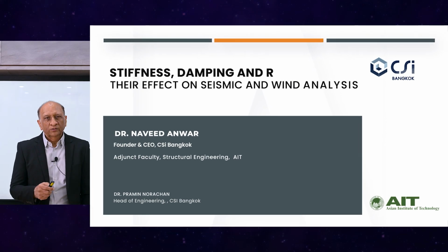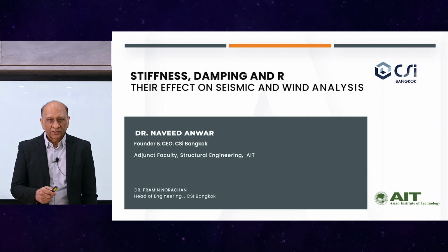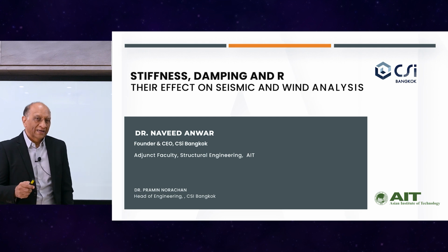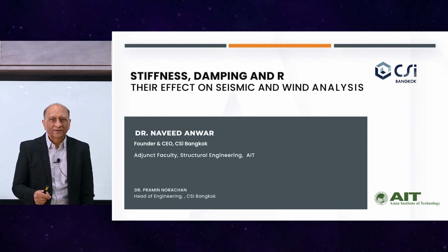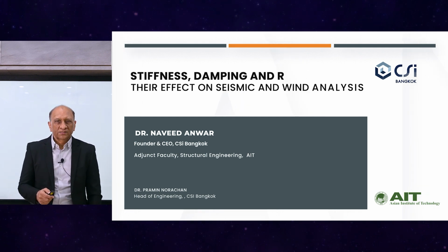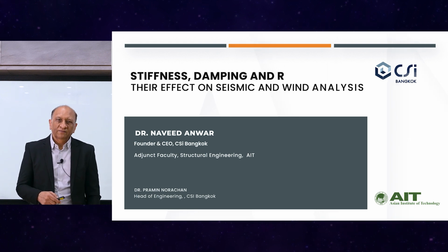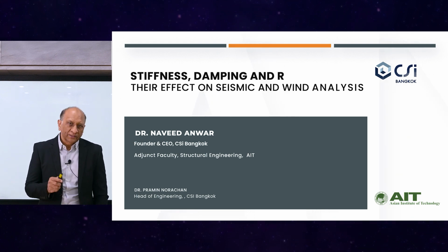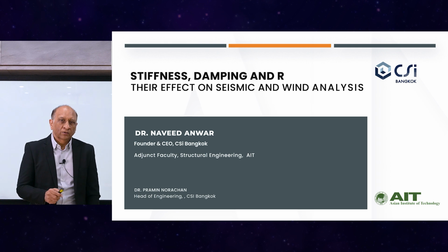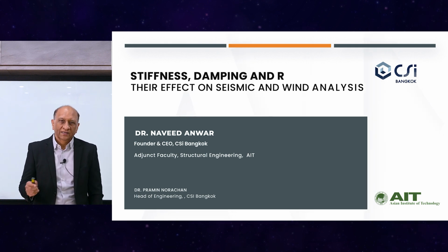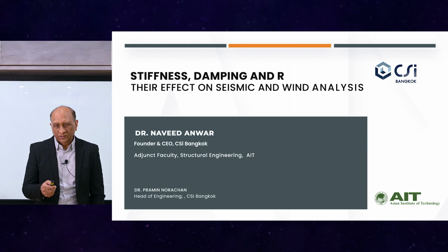Once again, we are going to talk about stiffness reduction, the change or selection of damping, and also the response reduction and related omega factors and CR/CD factors that modify the response from the true response to the design level response, and see how they affect seismic and wind analysis. Actually, the focus today I will keep on seismic, because wind is a different subject, which probably we will come back to in another talk.